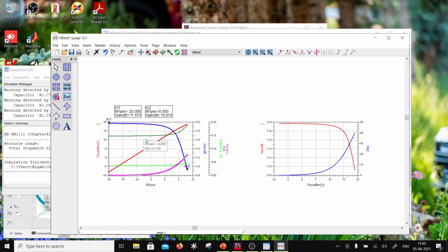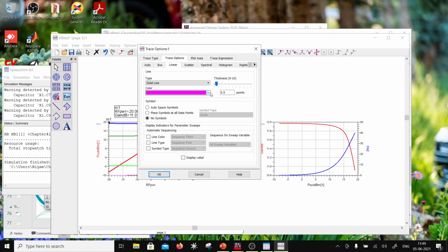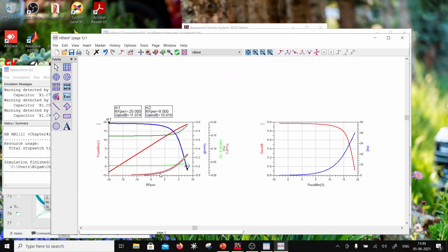And so what it says is that when you hit the transistor with a certain power, the DC conditions, the biasing conditions, would change. That's what this curve shows, that IDS goes up, right? Now in case of FETs, which are voltage mode devices, what do I mean by voltage mode devices? Because it is a voltage controlled current source. So the FET cannot be driven with a current input. It's only the voltage swing which is driving the output.